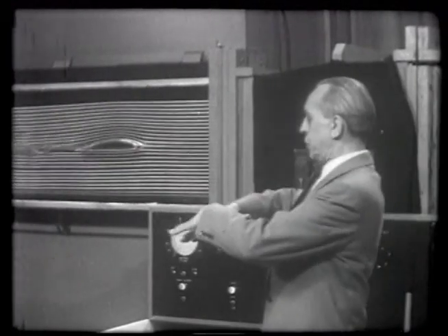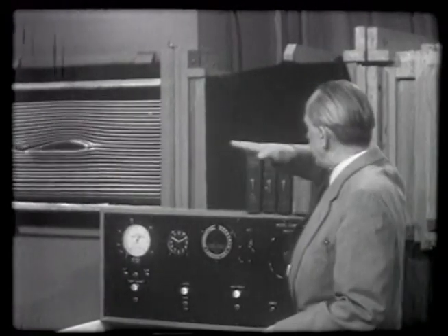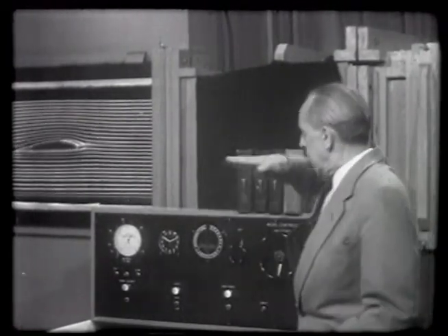So if you want to fly slow, which you necessarily need in takeoff and landing, then you have to tilt up your plane quite a bit to get this higher lift. And especially if you have passengers in an airliner, or other kinds of freight in your fuselage, you wouldn't like to change this attitude so much. You are much better off if you could fly your fuselage straight and still change your lift.